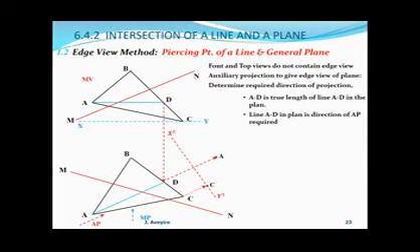Then we go to B, D. Note D and A have the same distances. Therefore, A and D by the auxiliary projection will be at the same point. Then we go for B. Now, the perpendicular distance from the front view from XY, we pick that and come to X1, Y1 and get that point there. If these projections are rightly done, then the edges AB, BC, and CA will all form a straight line.